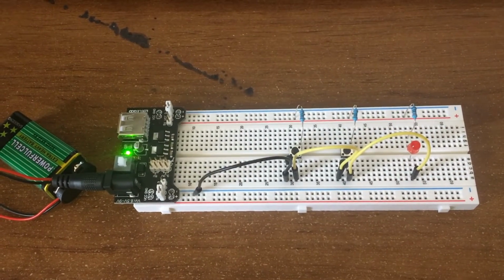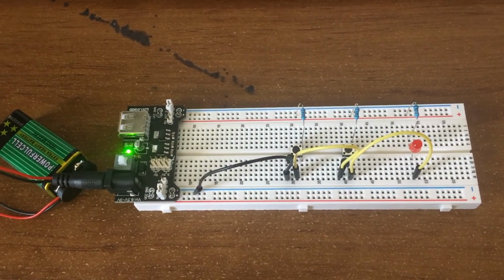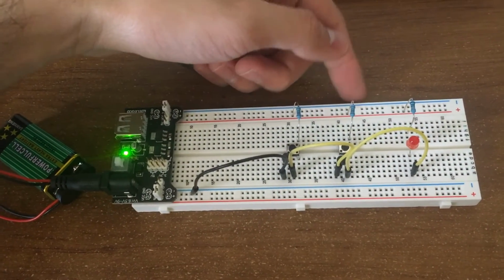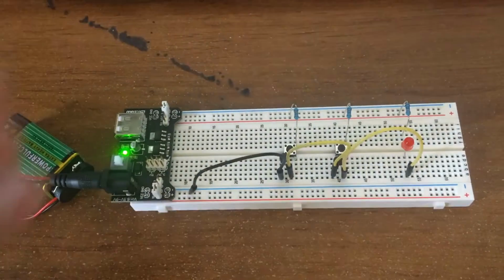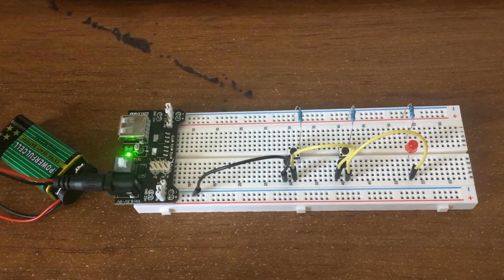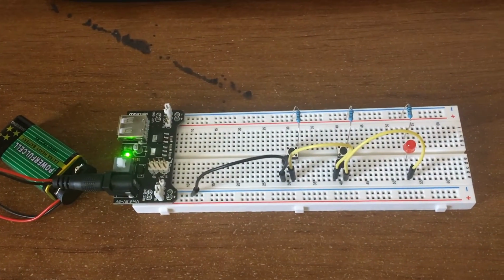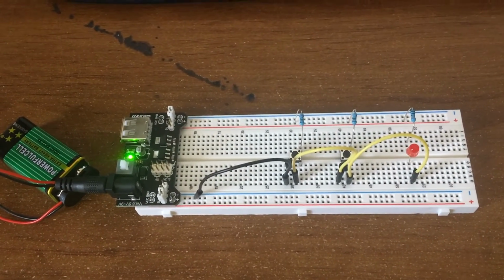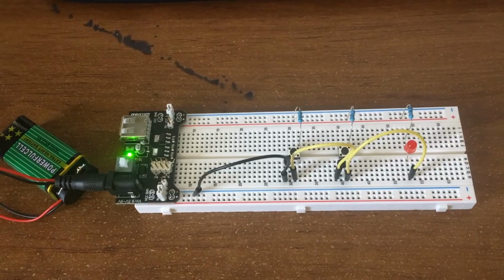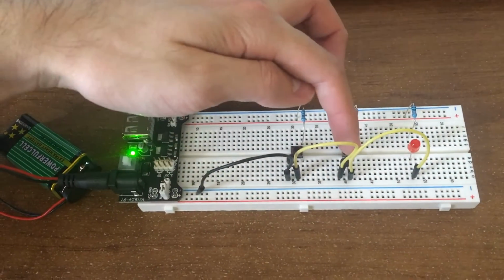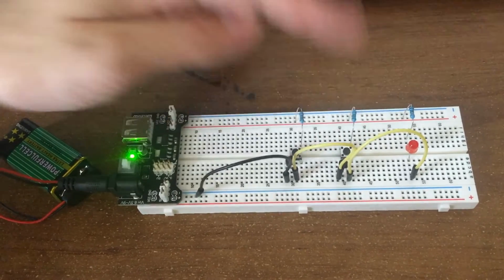Our third logic gate is our AND logic gate. Our truth table says that we have two inputs, A and B, and one output, which is C. Our first case, it's when both A and B are 0, meaning that C is 0. I'm not pressing anything, so right now the LED should be off. Our second case, it's when only B is 1, A is 0, meaning that C is 0. So as you could see, I'm pressing B here, the LED is off.